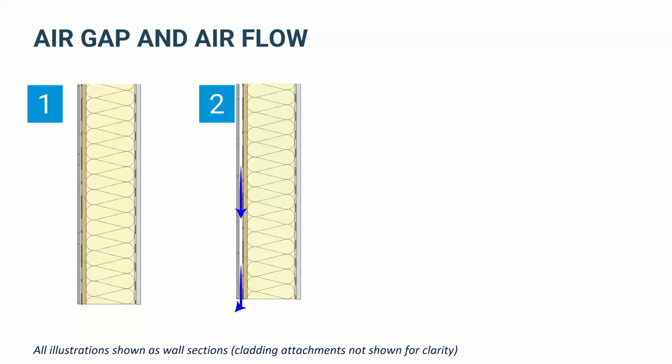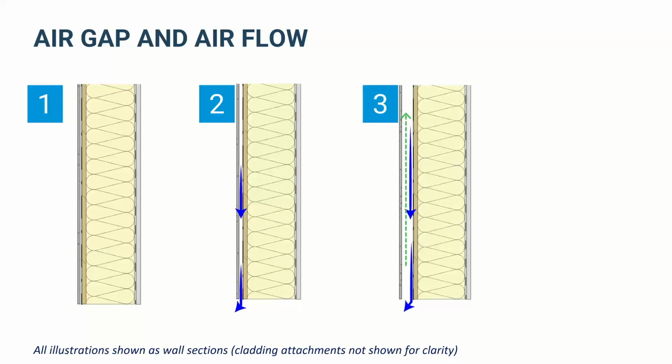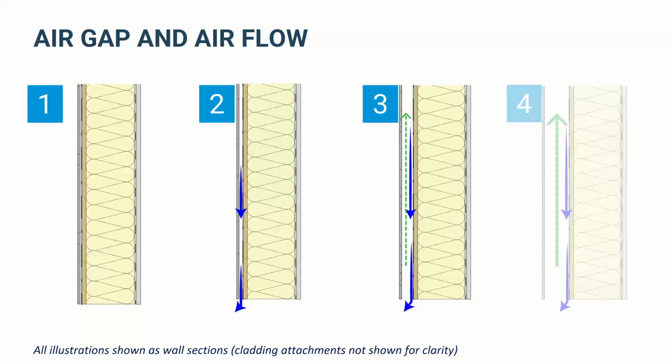Once you get into a really small gap, like a 1/16 to an 1/8 of an inch, that would be something like a drained house wrap. That can allow some drainage, but really not any meaningful airflow. And then once you get into something on the order of a 1/2 inch, that's definitely going to drain quite well. You're going to get pretty decent airflow as well. And then larger gaps, 3/4 inch and above, we've got lots of drainage, lots of airflow.